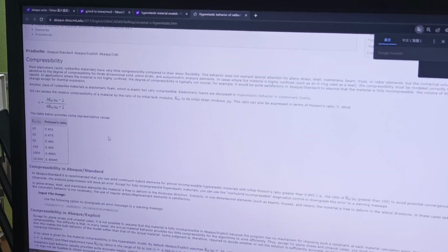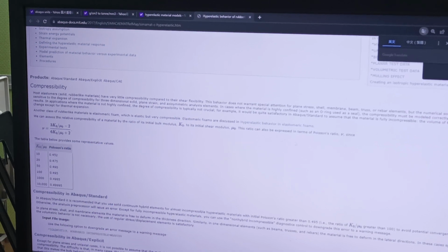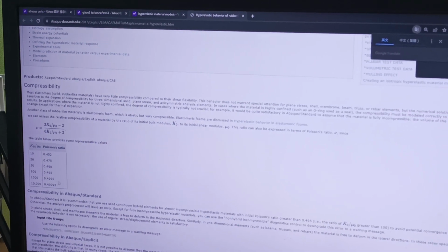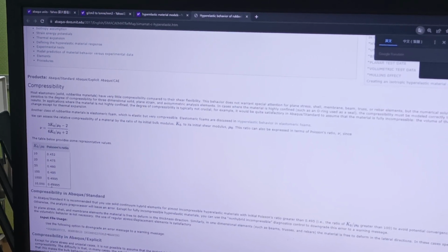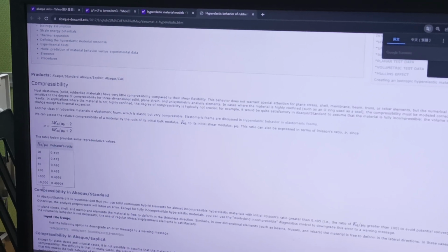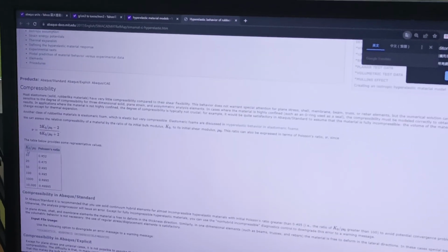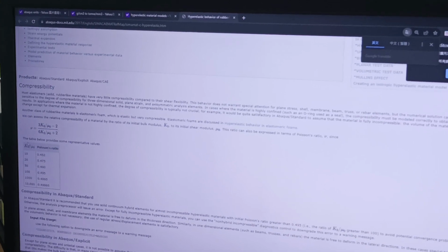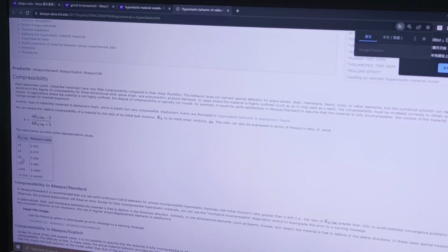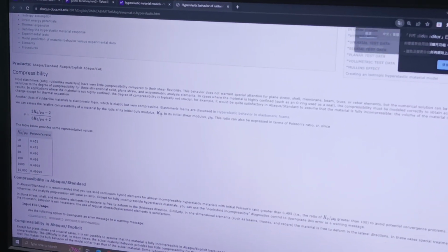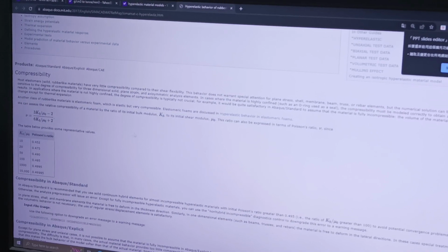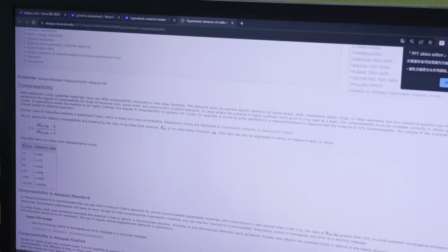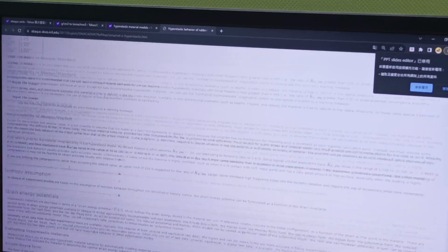So you can see here, Sam, I told you about the nu, right? You see the nu. If it goes increasing too much, you see the K naught by mu, this one is the bulk modulus, increases way high. You see the shear modulus here. So we need to set 0.48, 0.49, anything you can set.